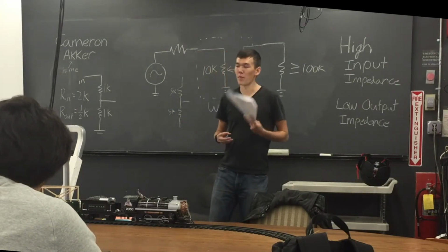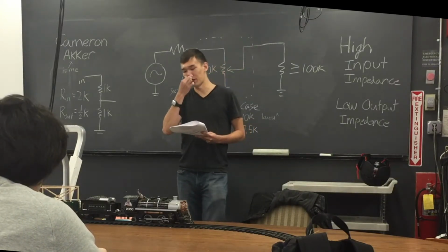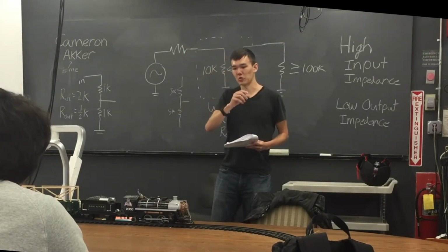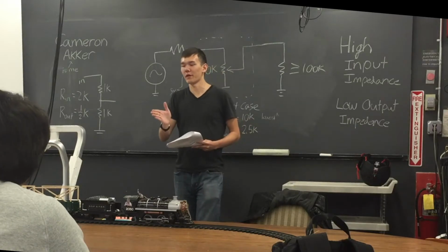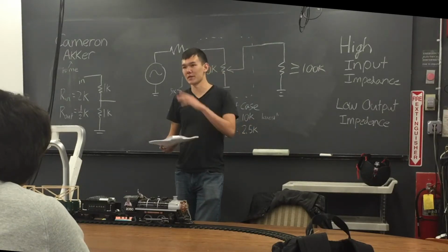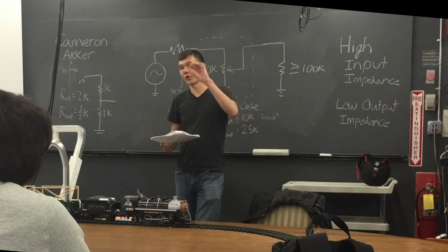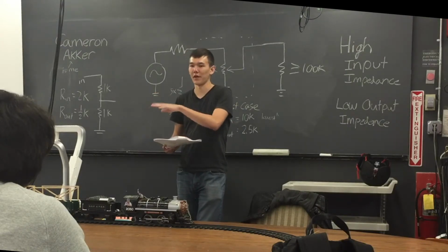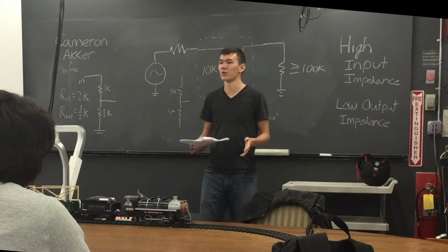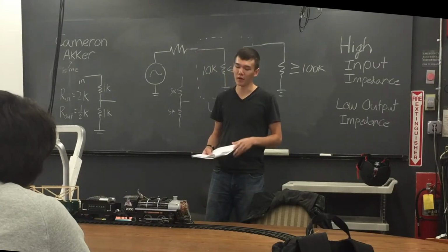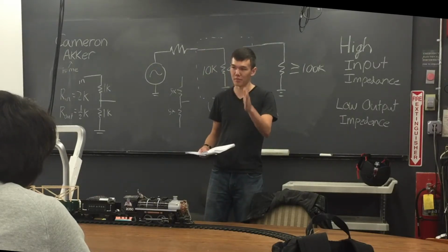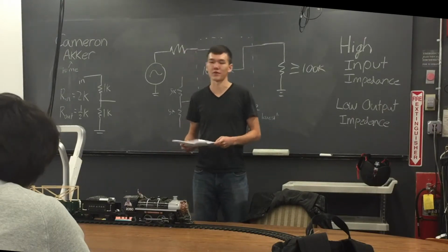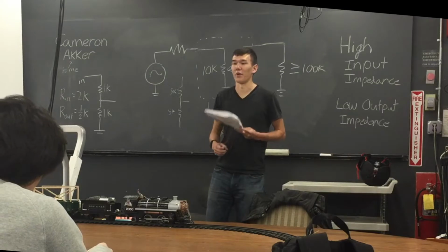The other thing is when we get to op amps and a couple other circuits, there'll be a concept of how much an op amp can drive. The op amp is a small component, it can only output so much current, and that's relevant because in some cases, you want to hook the output of the op amp to a high power thing and need a lot of current through it, but the op amp can only source like 25 milliamps or something. So current in that area is only really about making sure you don't overexert a part past the max current that it can output. Other than that, everything else is voltage.